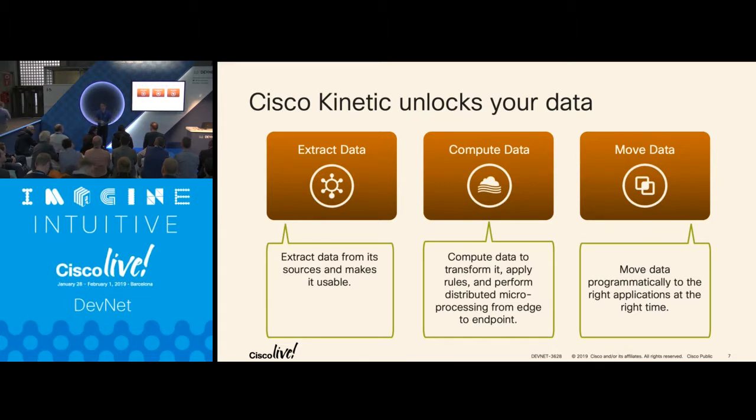Classical use cases, fridge monitoring. I'm monitoring a fridge temperature. It's okay if we are between 0 and 3 degrees. And I'm doing this monitoring every second. Do I need to send data every second to the cloud about the temperature of this fridge? No. I can just send a message every half an hour and say, I'm still there, I'm still monitoring the fridge, and it's below okay. For the last half an hour, average temperature 1.5 degrees. If you're below or above that threshold, then you start sending messages immediately. That's a very simple example of how you can do filtering in the edge, okay?